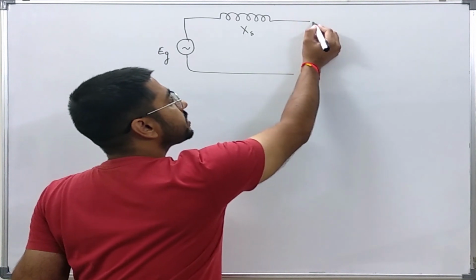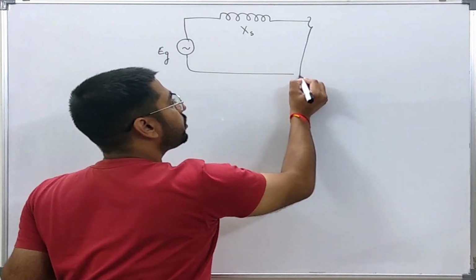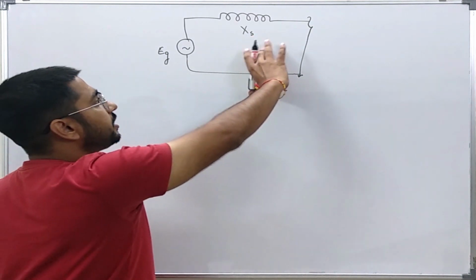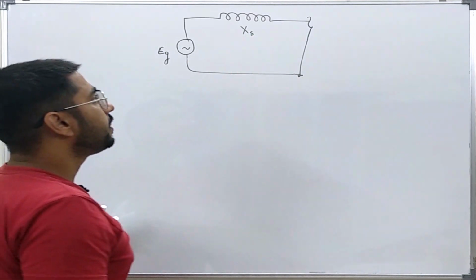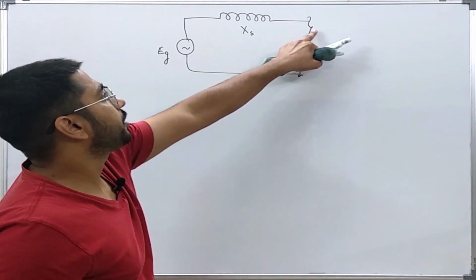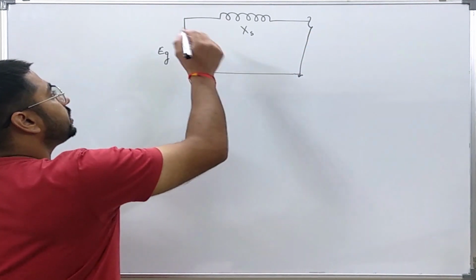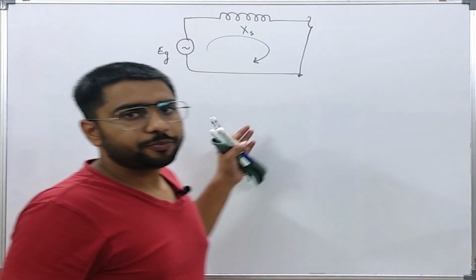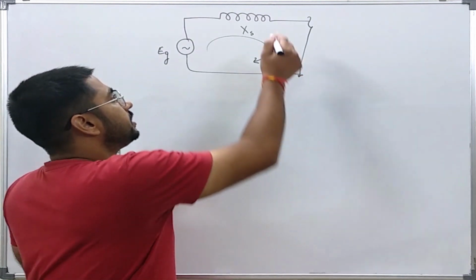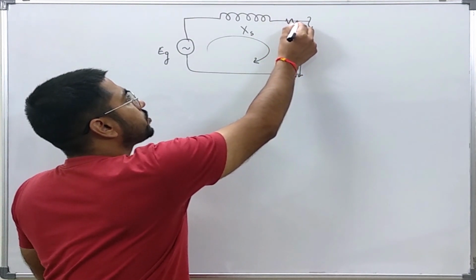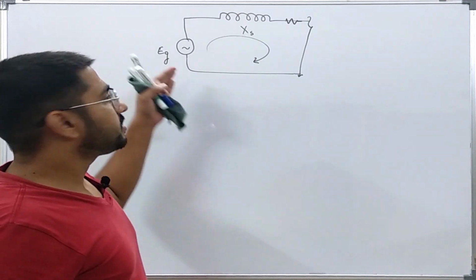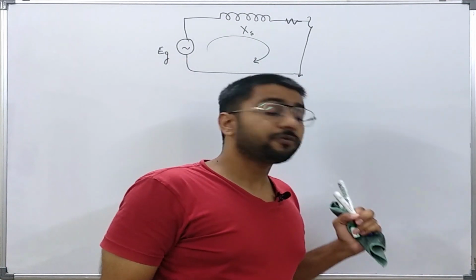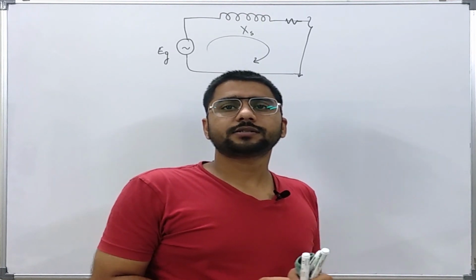Whenever there is a short circuit fault on the terminals of the synchronous generator, I am showing the per phase network equivalent model, the network is kind of purely reactive. If I take some small resistance also, we will see that this circuit should behave like an RL circuit only, which we have seen in our previous lecture. But what are those differences? Now let us discuss those.